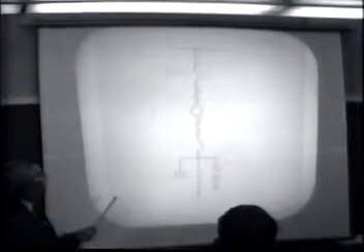Now we can show different electrical designs of substations very readily with our single line diagrams, since these are the simplest diagram that we can use to show the various components of an electric circuit. So we can refer to sketch number 1 again, which represents probably the simplest form of substation configuration, that being the single breaker, single bus, or the radial system.